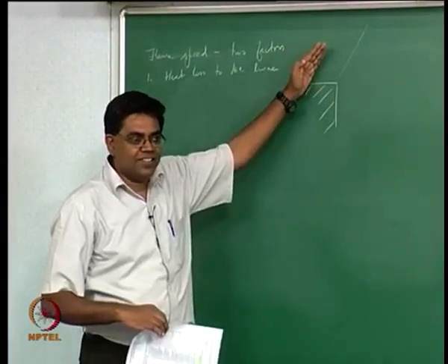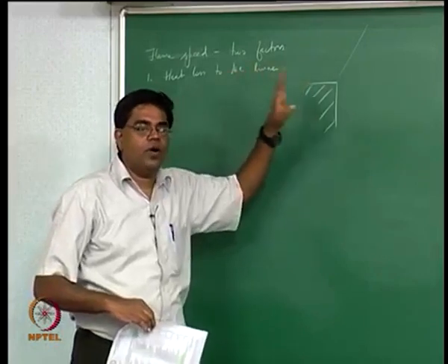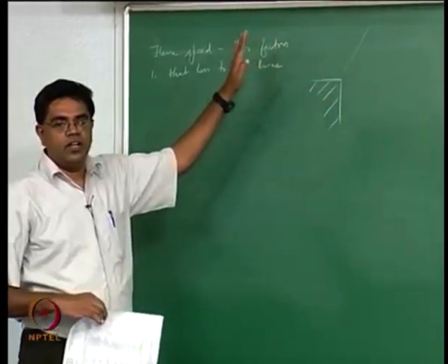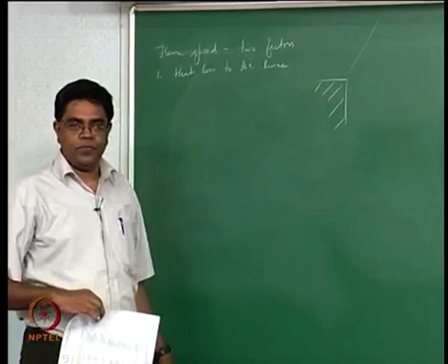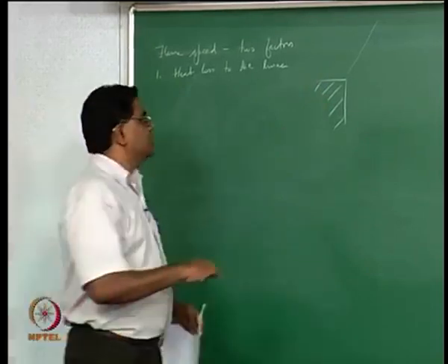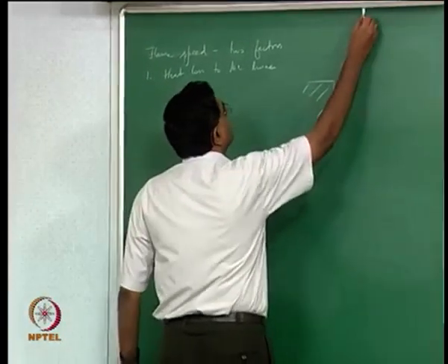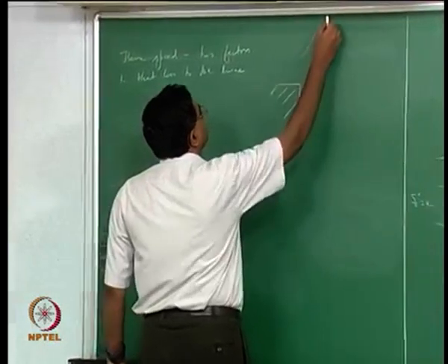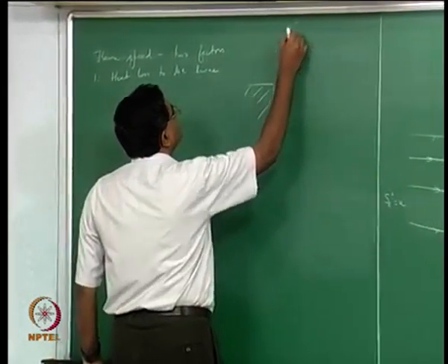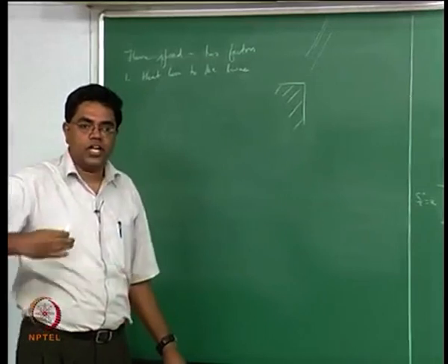You now have to worry about how the preheat zone looks, how the reaction zone looks. What I know for a fact is that far away from this burner rim I'm going to have a certain thickness for the flame, and the preheat zone is going to be thicker than the reaction zone, the larger the activation energy.